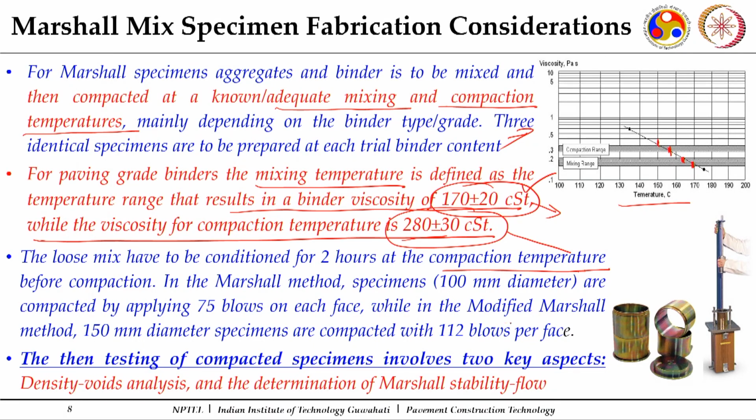So it remains at that higher temperature for a good period of time. To simulate how much aging happens, and how much binder absorption happens into the aggregates, this conditioning is done. Thereafter we compact by pouring the loose mix into cylindrical molds and giving the standard blows as specified, following the Asphalt Institute manual series. IRC 111 also gives the method, and ASTM and IS guidelines are also there to conduct the Marshall method of mix design. The blows are applied on both sides.